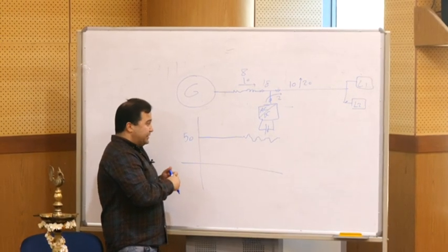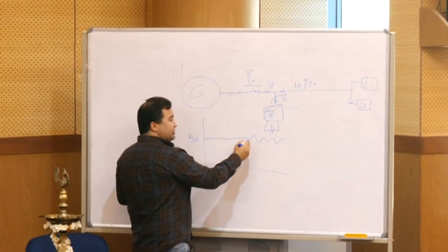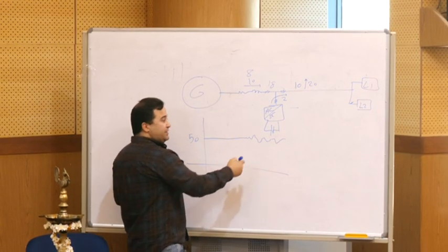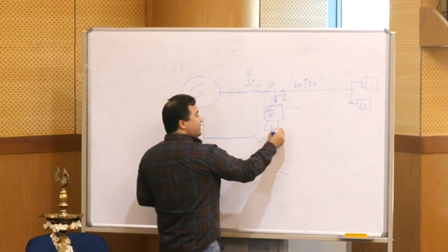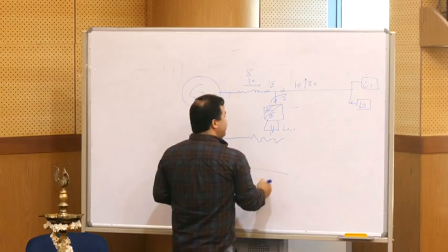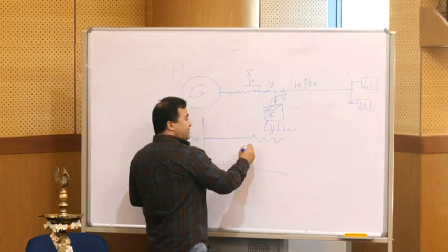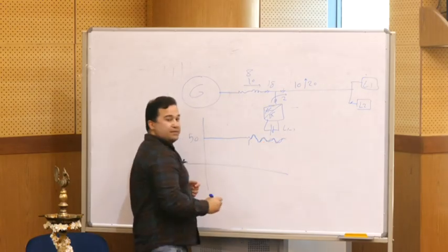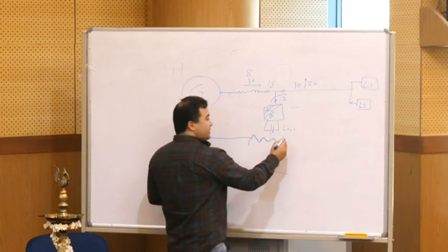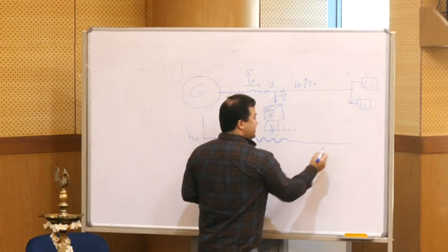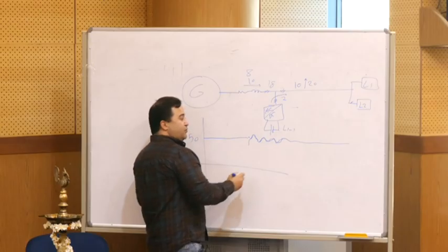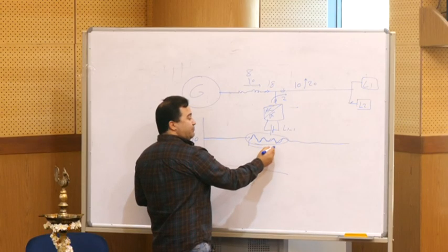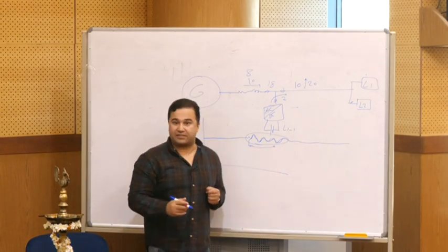But what is happening is that when we have load changes, slow or fast, when this fast change happens and we have a lithium-ion battery, then it cannot supply the load changes so fast, because we need to pass this transient and reach the steady state. So for this case, we have transient stability problems, which is not good for the sensitive loads.